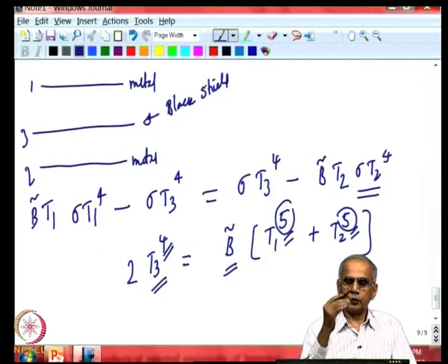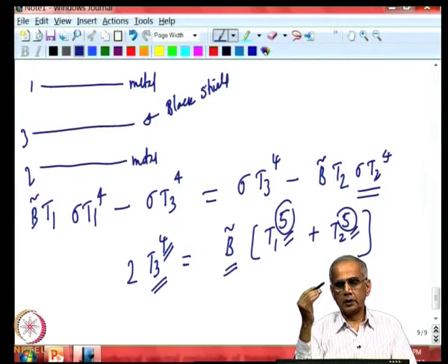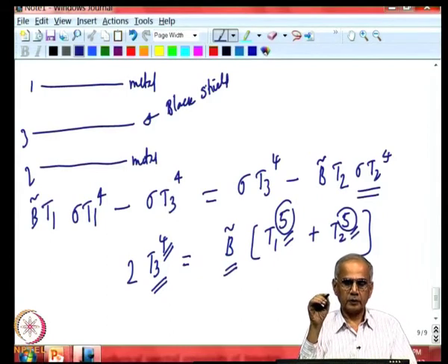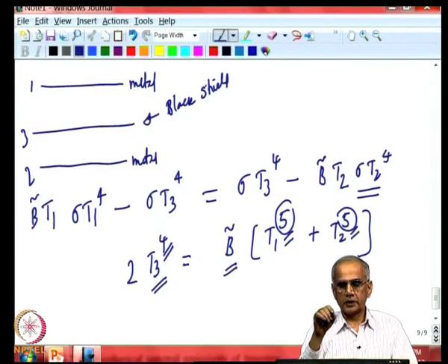So, this gives you two examples here, one in which there were a metal shield in between two black plates, the other the black shield with two metal plates, and the results are somewhat different, indicating the important role played by the spectral variation of emissivity and absorptivity of the material.